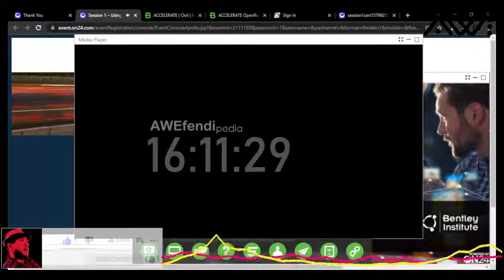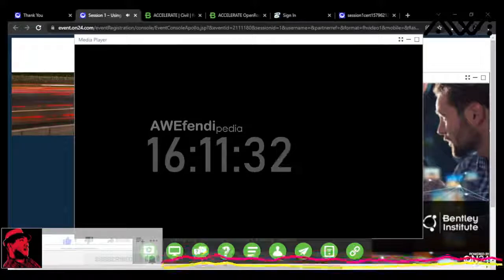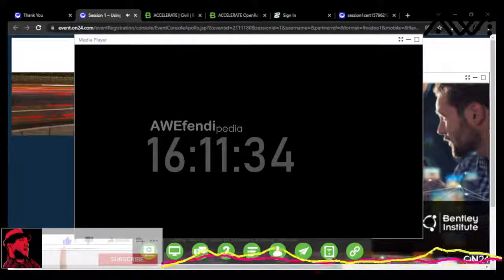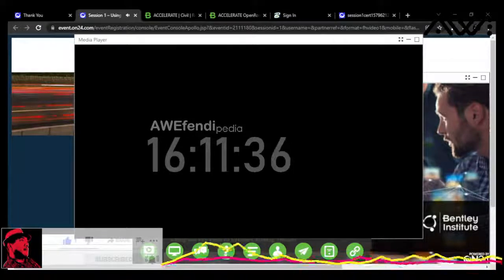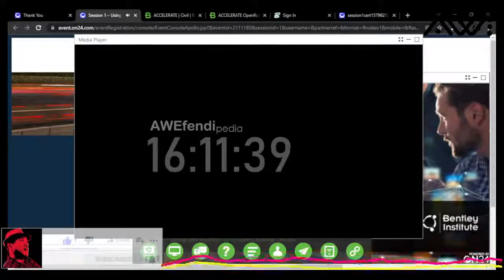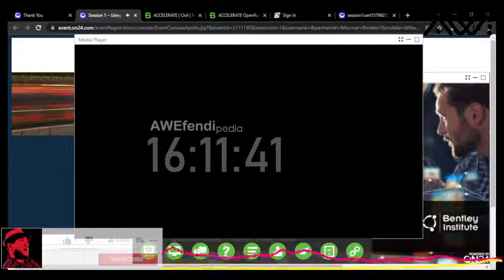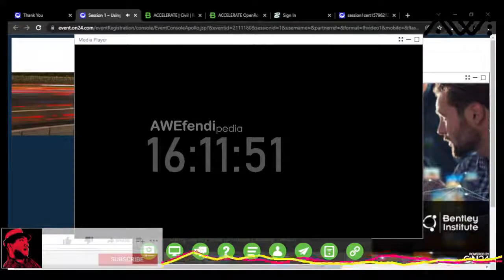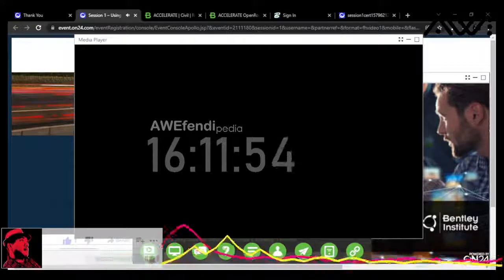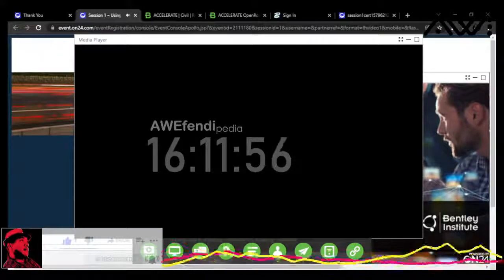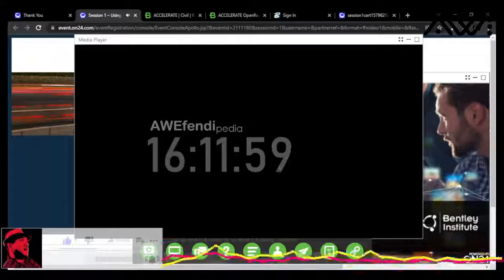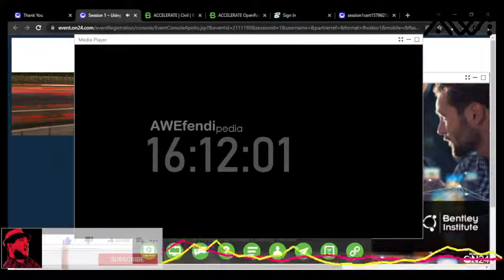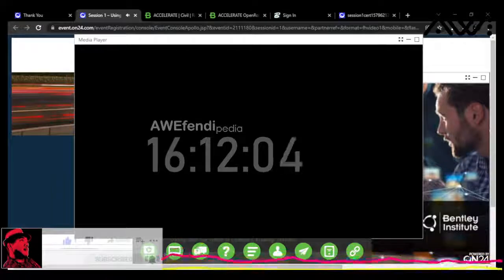And so what I see here is a little side road down here. I see my creek running through, and it looks like my bridge is lined up good. I see some side roads here. I see a median cut through here. So it looks like my survey data is matching up geographically with the Bing maps that are streamed in here in the view attributes. So it looks like I'm located good. I've done a little bit of import. It's located correctly. I have good graphics drawn already. So I think I'm good to start doing some edits now and really tie down this survey information.